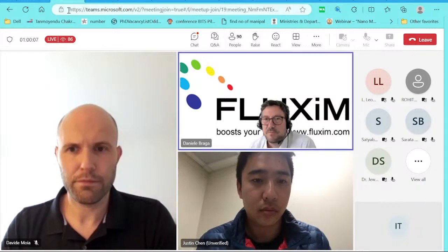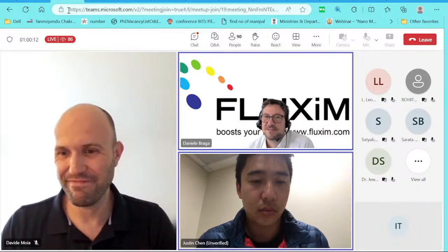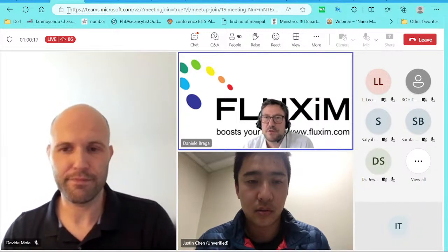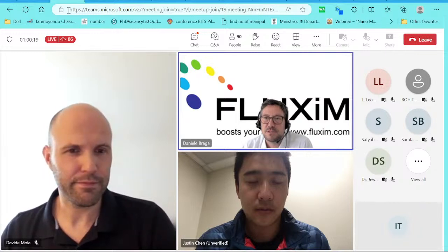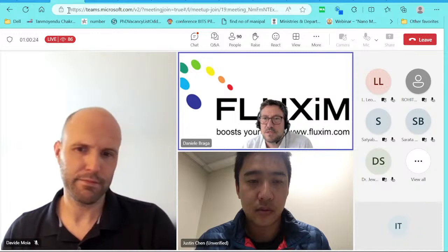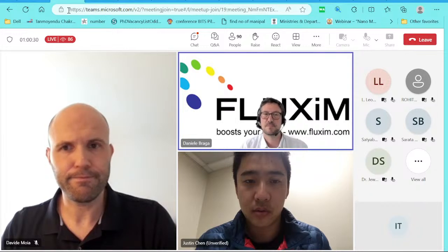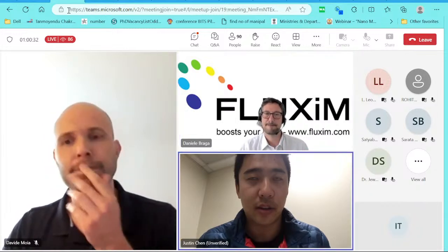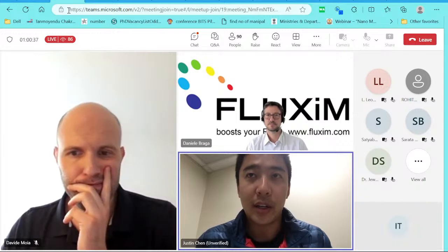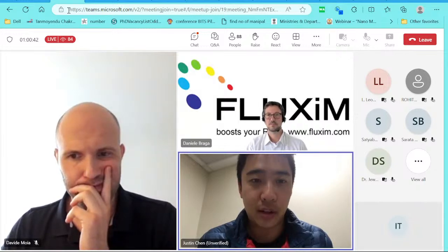Thanks. We have plenty of questions for you, Justin. This one, interesting. How to overcome the challenge of pinholes using the spray coating method for thin layer BCP deposition? You have a layer of PCBM under the BCP. Is this intended to avoid the leakage from the BCP pinholes? Yeah, if I understand correctly, the pinholes are definitely challenging. I think for us, it was less an issue of the spray itself, but more about keeping the dust and particles out.